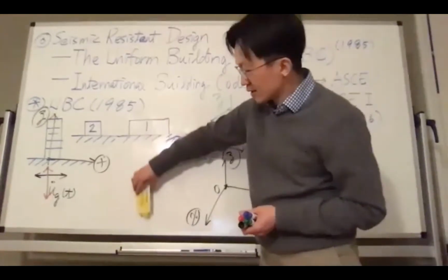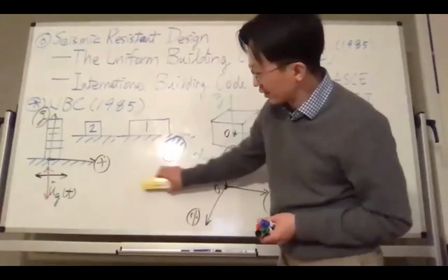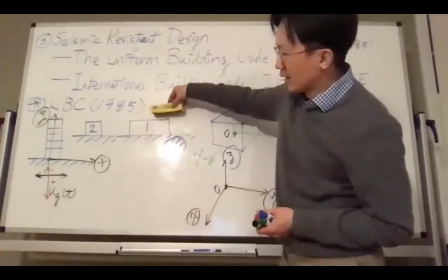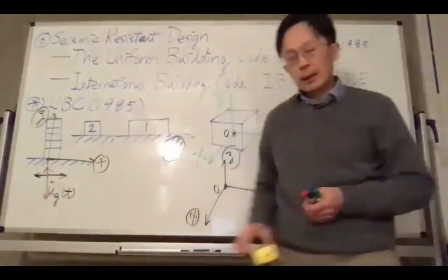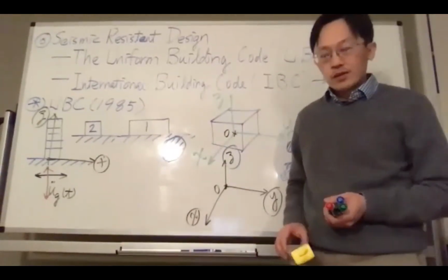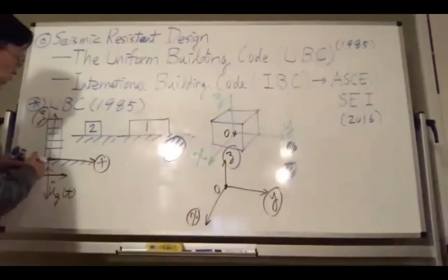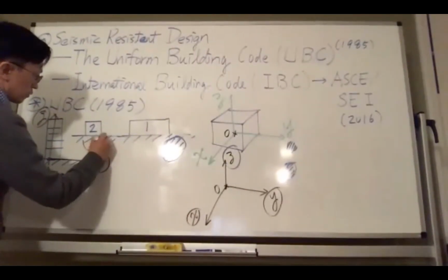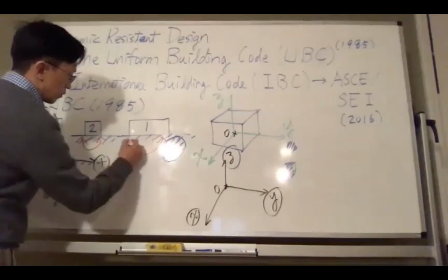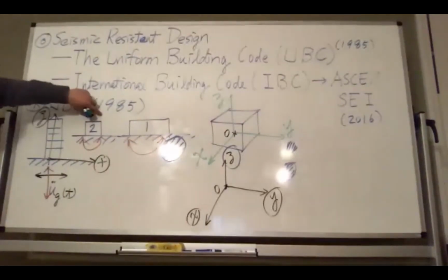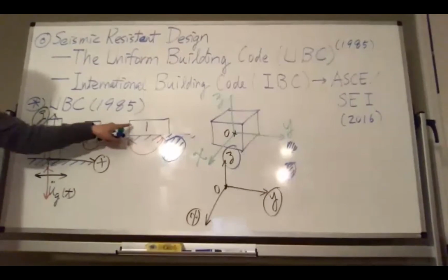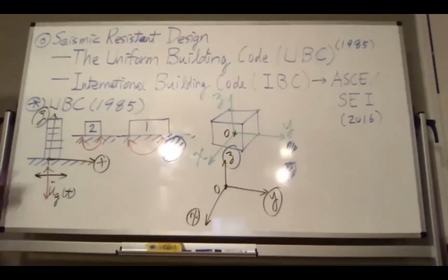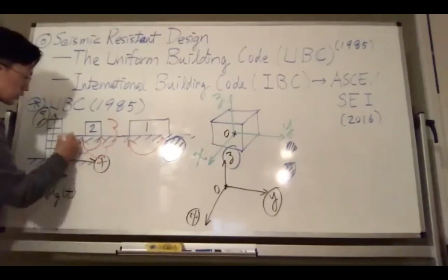Case one is this, so it shakes horizontally like this. Case two is like this. So when case two moves, with the same moment, it has a shorter distance, so it's going to produce a greater force acting on or transmitting to the columns of this building. Suppose they are buildings. Which is why this is more critical.